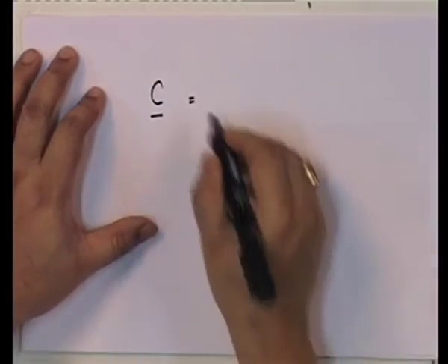So, therefore, nowhere does phi_n have to satisfy C. It is just that for us to ensure that we get uncoupled modal equations, we need it to be orthogonal. So, therefore, the C matrix has to be of a form such that